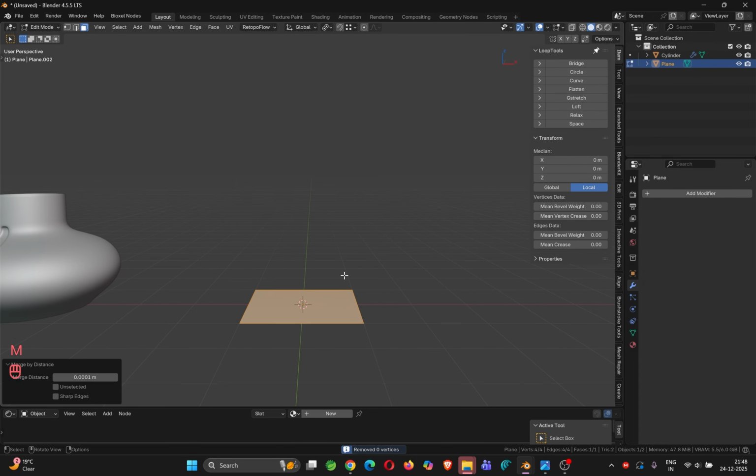Another thing I forgot to mention. With the screw modifier, it creates duplicate vertices. So what you need to do is use the weld modifier so that it automatically removes the duplicate vertices, and you don't need to apply merge duplicates again. Now if I apply some subdivision, you will see I am getting roughly that shape.